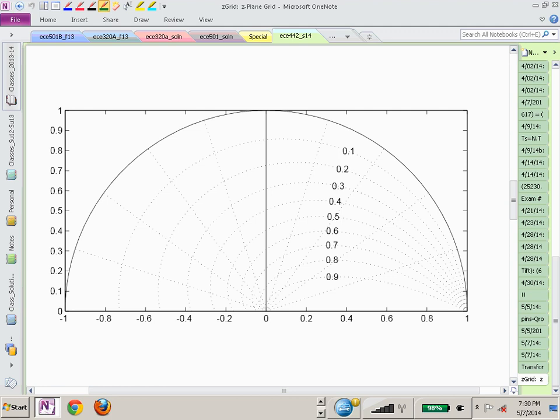If somebody said, oh, your closed loop poles are at, let's say, 0.6 plus j5, now you're about right there for your pole. But now you have a pretty good feel for what your zeta value is, right? It's one of those logarithmic spirals, and you can just eyeball it to get a good fuzzy feel for what you're going to calculate or numerically determine.